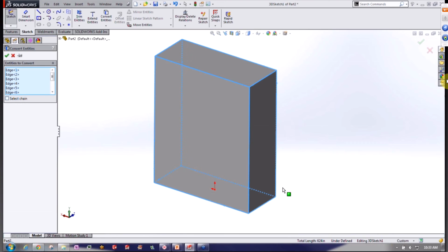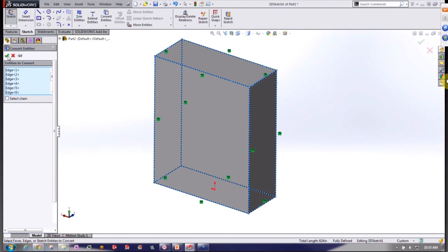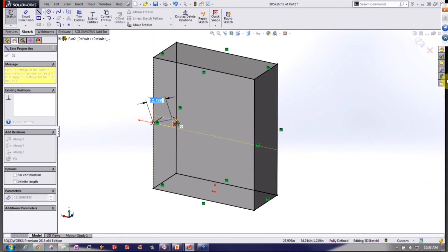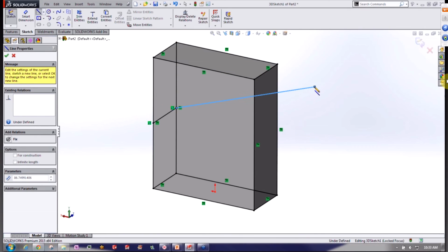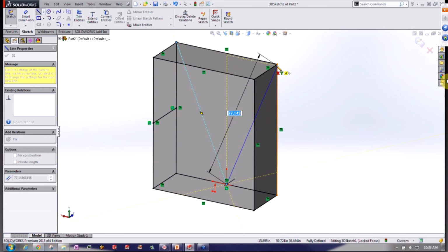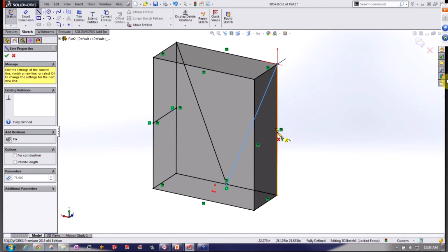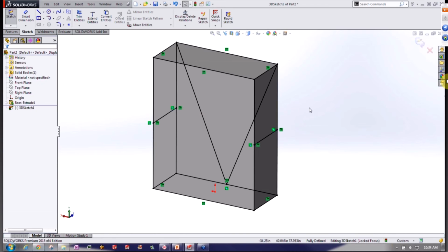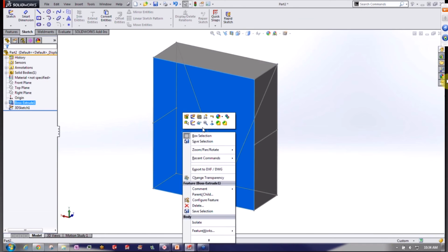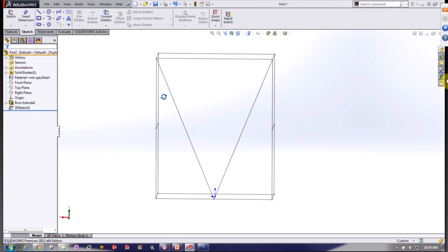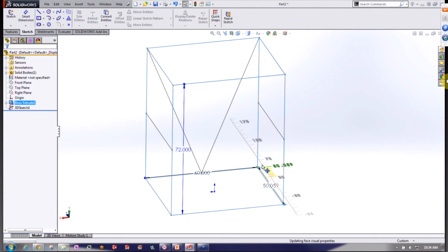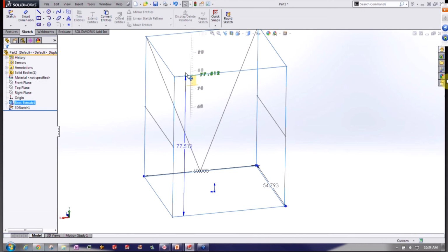But this is a nice method to get you comfortable with it. I can convert those entities, and I basically created a very identical 3D sketch here, where now I can go through and connect the rest of my lines, making the same identical shape I had before. But I didn't have to worry about which plane I was in or anything like that, because the extrude I created was managing that for me. And then I have the same great underlying single 3D sketch. I have that body that I can hide to get out of the way, and now I'm looking at the same type of frame that I can adjust. Right? So I can adjust these distances and everything just as I could with my other method.